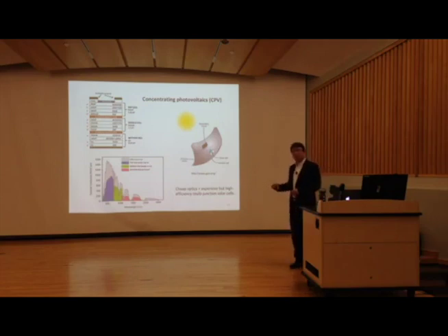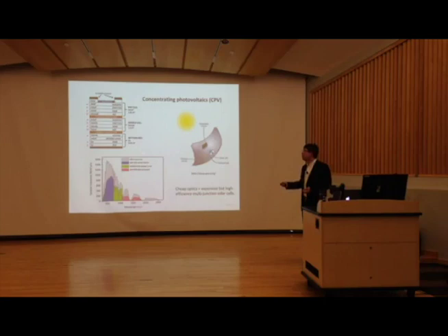So this is the technology people propose. Because the solar cell itself is very efficient but also very expensive, they are going to have the solar cell be very small, integrated into a big system. All these are very cheap mirrors and lenses. So in this case, you combine cheap optics with expensive but high-efficiency multi-junction solar cells. Maybe the ratio is 100:1. In this case, you concentrate the sunlight onto a small area of solar cell. So the solar cell cost is high, but in terms of the whole system, it's not that high.